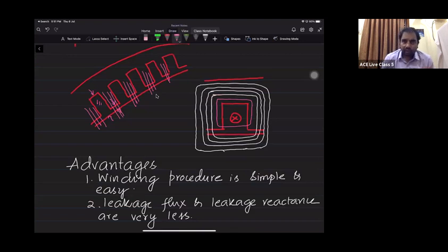So can I say here, because of the wide opening of the slots, the air gap flux distribution is non-uniform. If it is non-uniform, harmonic torques are produced, and these harmonic torques will give rise to noise and vibrations. Is this point clear? Confirm me, all of you.